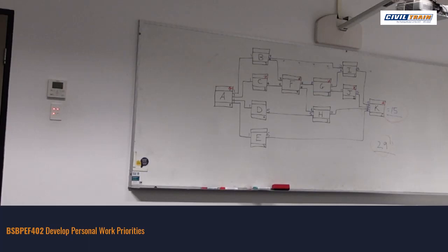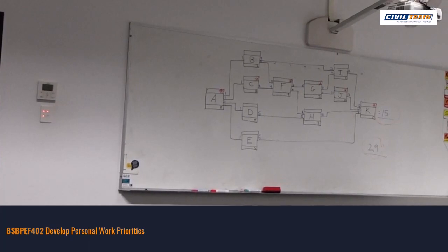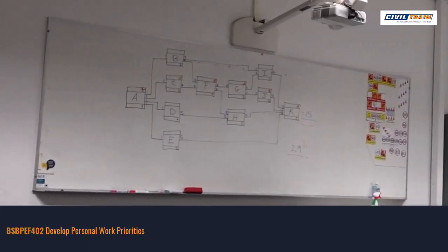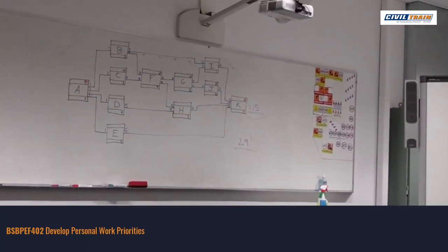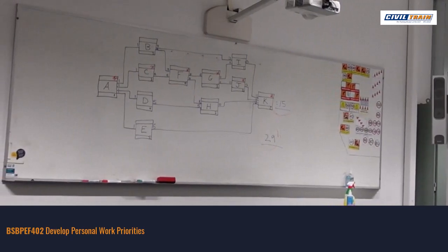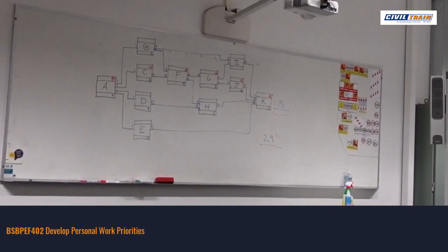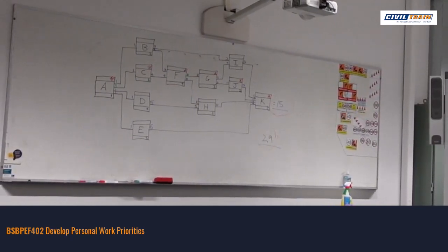Because if it was calculated on the critical path method, it's the minimum number without anything going wrong. There's no buffer in that in regards to leniency, unless you have put contingencies in. So it's 15 days. June, July, I'm going to add 2 days for wet weather, and pre-plan that part of the process.